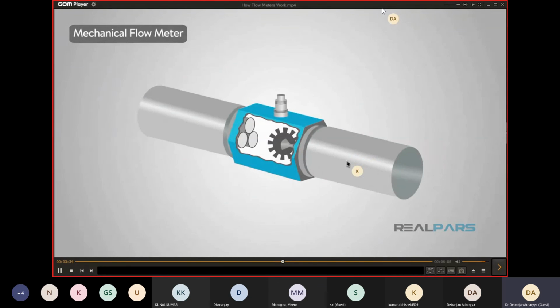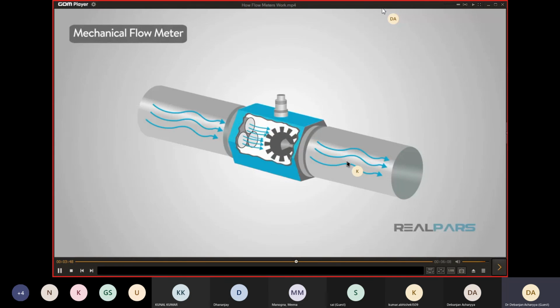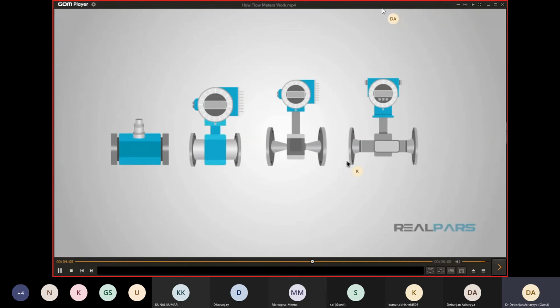Same principle as the internal paddle. The faster it's rotating, the more flow going through the pipe, which in turn sends a graduated signal to your PLC. That's the simplified version, but there are other factors that the manufacturer takes care of for you. Piping size, water temperature, etc., all go into a formula that will correlate the rotational speed with a unit measurement such as gallons per minute. Yet still, there are other types of flow meters.